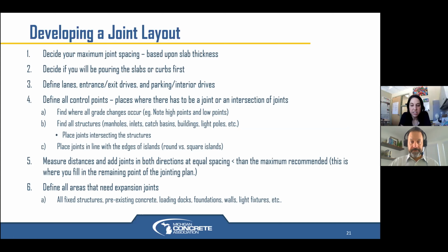Go ahead. I was going to say, when you're repairing an intersection of 4 different slabs where each slab has spalled in the corner and you make a square patch, would you say it would be smart to at least score the lines through your patch? That's similar to MDOT's longitudinal full depth centerline repair detail, where they do, I believe it's a 30-inch minimum wide patch to be able to get drills down in the hole and drill tie bars into the existing slab.